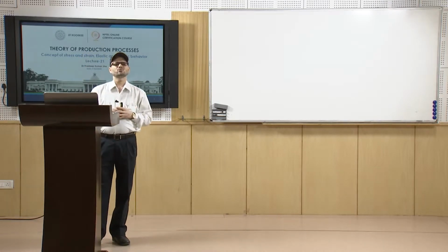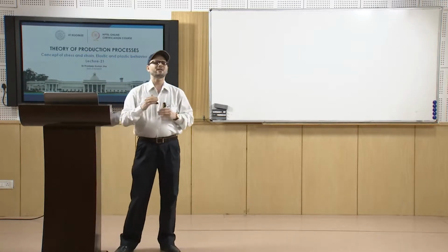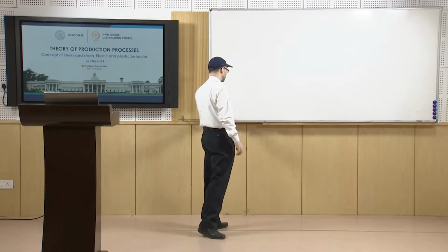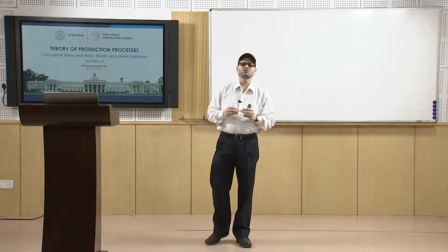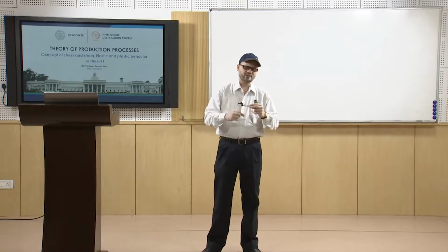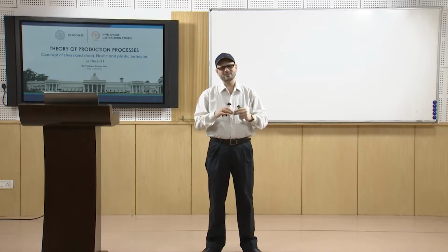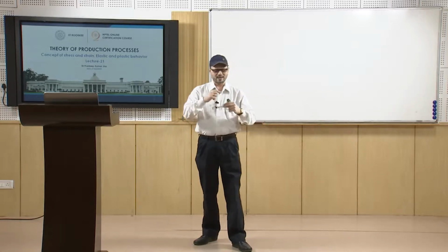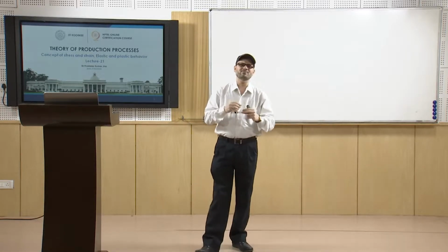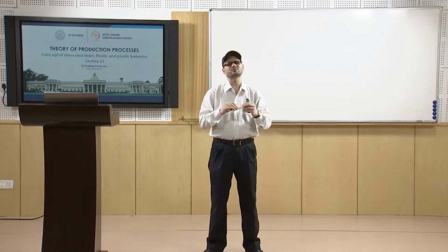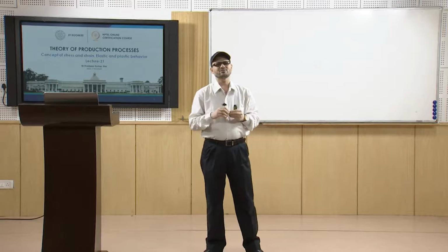So, basically, what is stress? Stress is that internal resistive force acting over a certain area. So, that internal force is the integral of the stress times the differential area over which it acts. Suppose you have any member and you are applying a force on it. If you take any section, and if it is in static equilibrium, then on that section you will have the resistive force which is working against this force. So, that is why that force is acting.